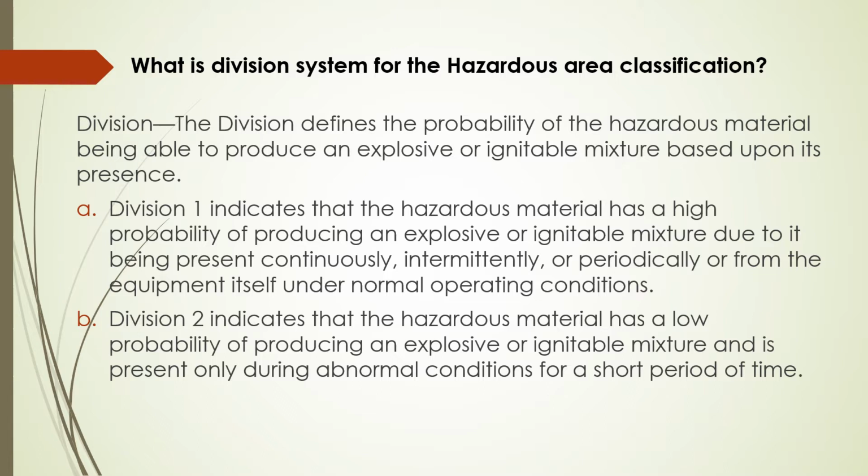Division 2 indicates that the hazardous material has a low probability of producing an explosive or ignitable mixture and is present only during abnormal conditions for a short period of time.